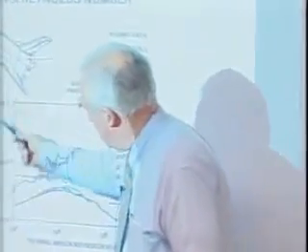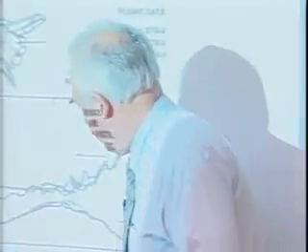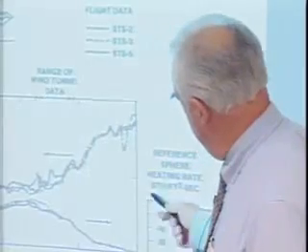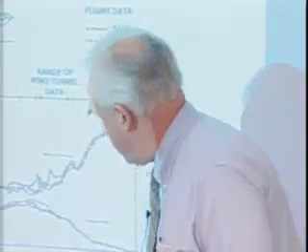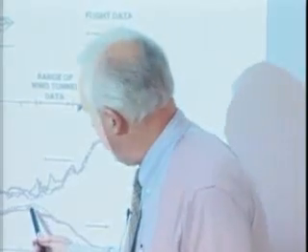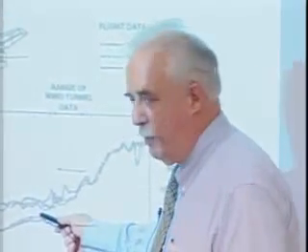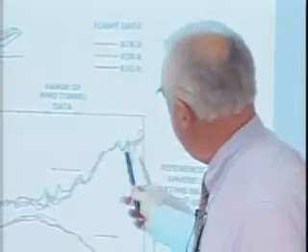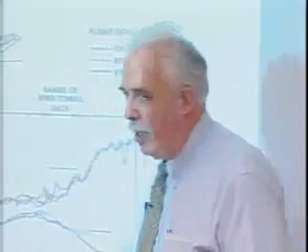This is normal shock versus heat transfer, film heat transfer coefficient, basically heat transfer log. This is the heating shown here as a function of normal shock Reynolds number. Now remember I said we designed the trajectories, so we went up here and spent 10 minutes and then came down as normal shock Reynolds number. And here are 3 trajectories with the heating on one location on the lee side.